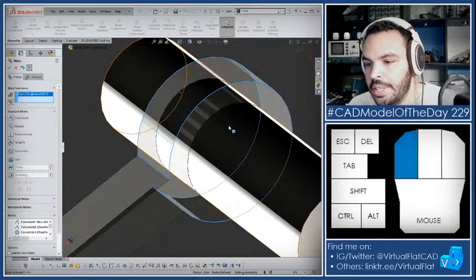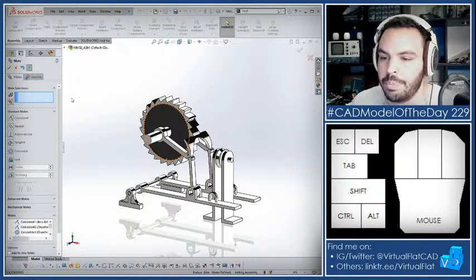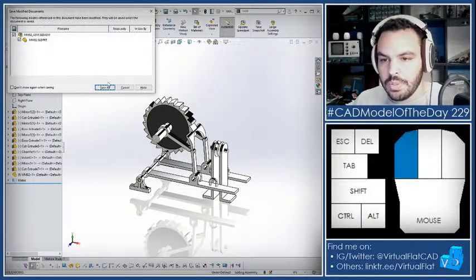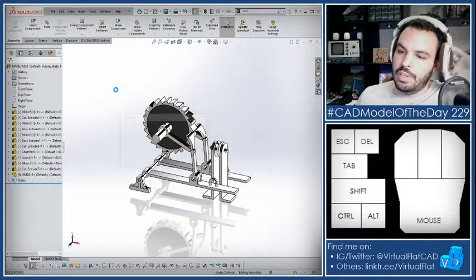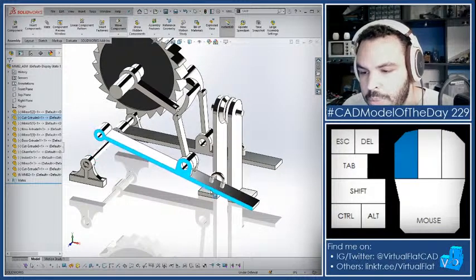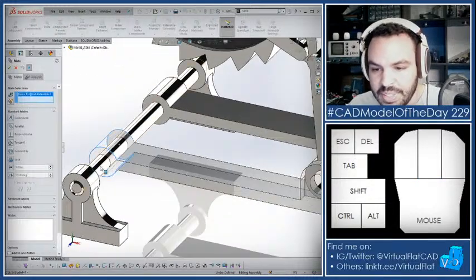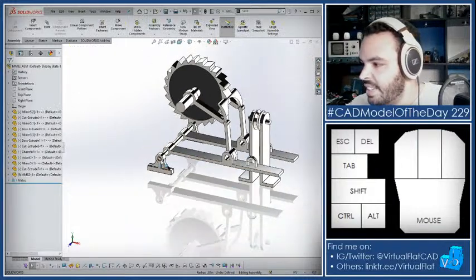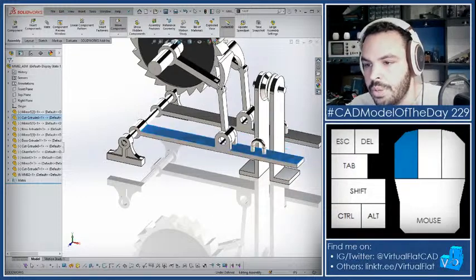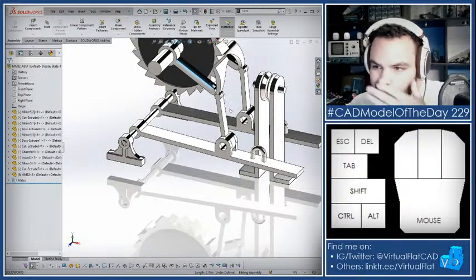But I'll tell you what, I like this a lot better than having to place every single component. Like, everything's already in place and we're just locking it in place pretty much. Save, and I'll try and start moving stuff around to see if my work is correct. So if I move this, it should only move, well, yep. Looks like I am missing a mate here. Immediate fail. All right, so that seems to be working normally, albeit there's no collisions, but we'll fix that.